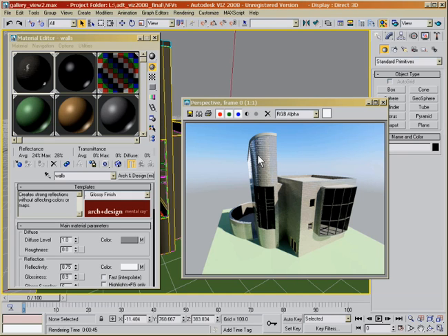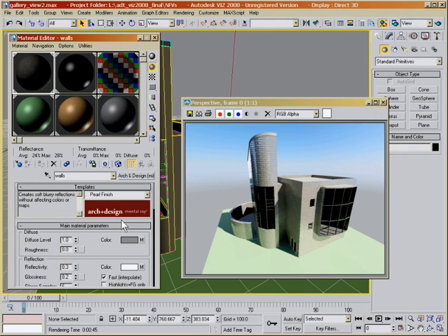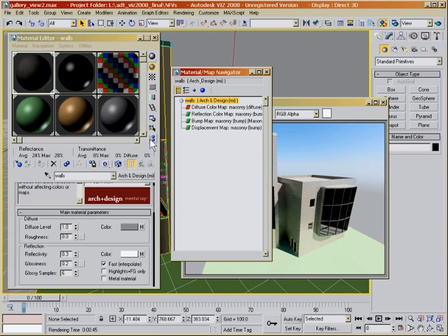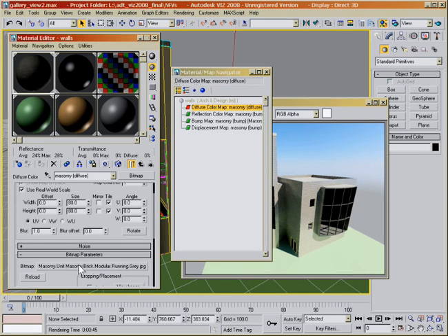As we see, the material is still the same, but there is much more reflection on the wall surfaces now. Maybe too much, so we select the pearl finish, which is somewhere in between. And as with any other material, texture can be changed by replacing both diffuse and bump maps with a custom brick texture.